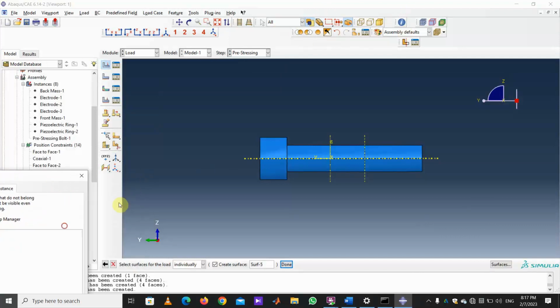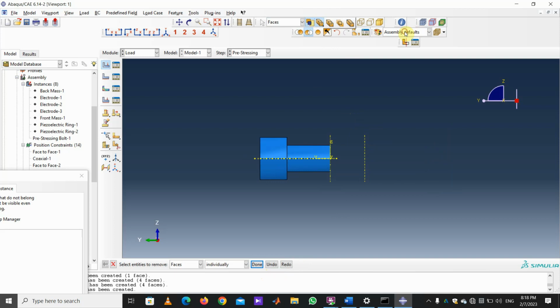Okay, before that, as I mentioned earlier, I forgot to select all entities, yes. If I select all entities, which is active now, when you select a portion of a space, all the faces, both interior and exterior surfaces, will be selected and will disappear.